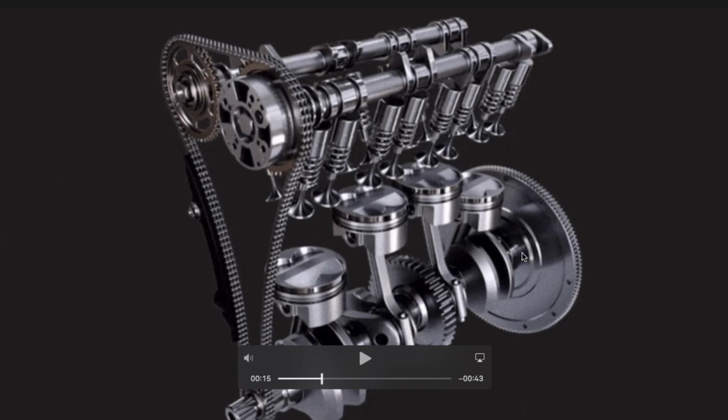Now you might be asking, Haik, how do you know this? Well, this engine has something called variable valve timing. And what happens is when the engine reaches a certain RPM, a certain revs per minute, this piece, which is an actuator, it's actually hydraulically controlled. This is what will change the timing profile and will allow this part, which is the intake valve, to stay open for longer, so your engine will actually have a much better combustion, therefore giving you much more power. So it will be able to move the piston up and down much stronger. So the more air, the more power you will get out of your engine.